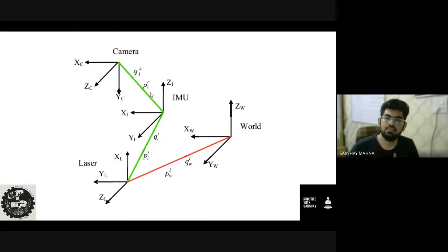To increase the reliability of the sensor, now sensor values can have an error up to a certain limit. So to create a reliability system, we use an algorithm called sensor fusion. As the name suggests, we are going to fuse the sensor values coming from the different sensors. For instance, we are going to combine the camera image that we had and the laser scan that we had to get a final reading that will be more accurate, as the errors will be averaged out and cancelled.